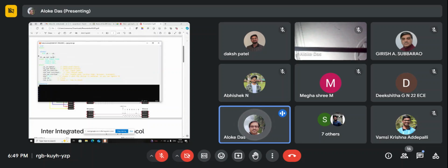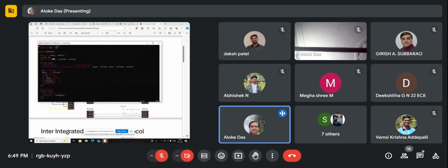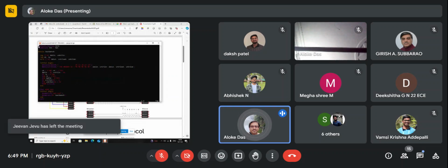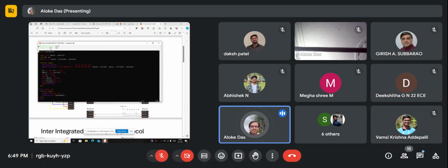That means it will give you a time period of 20. And if you make the time unit 1 nanosecond, it will be a 20 nanosecond time period, that means 50 megahertz. For RTL simulation, the timing doesn't matter that much. Whatever clock frequency you use really doesn't matter.